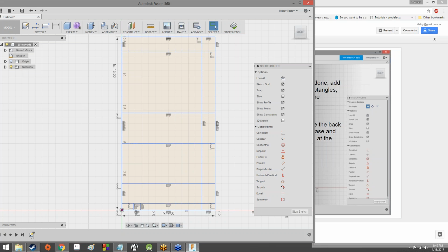If you could, okay. You shouldn't have to dimension three sides of the body because it's a rectangle, so doing two sides will be enough for the computer to assume what all four sides are going to be dimensioned. Know what I'm saying? Because right now all we're doing is a side-on view of this bookcase.